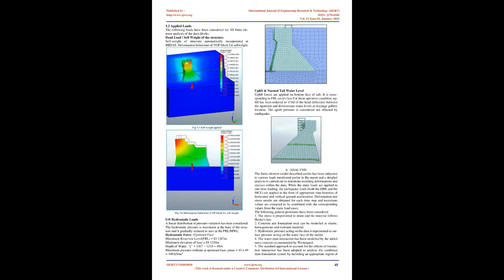For dynamic analysis, realistic results shall be obtained when mass of foundation is also considered along with material damping. Modal depth below dam founding level where the seismic wave is acting plays an important role in getting close to actual results. However, getting these parameters precisely is another challenge. To be on the safer side, foundation with no mass and 0% damping has been considered. It will result in higher induced stresses and reactions than actual for dynamic seismic loads.